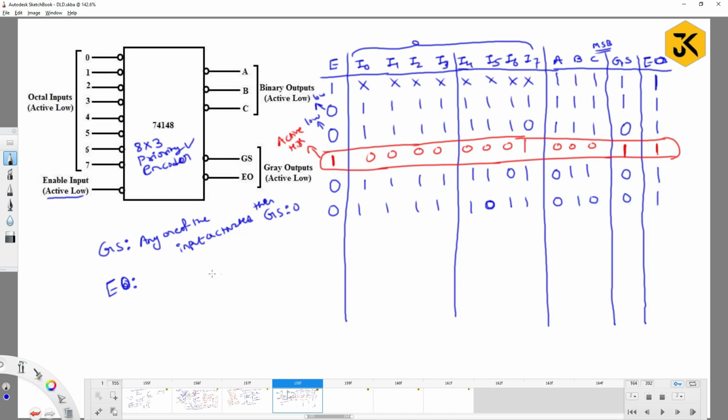Right? But the point you have to understand one thing. As I am saying that this is a kind of a priority encoder, priority encoder. If I am going to get 0, it is okay. What about this particular case? It should be don't care, and here also it should be don't care. It should be don't care, right? Fine. So next one, 0, 111, 0, 4 ones. This will be 0. This will be don't cares.